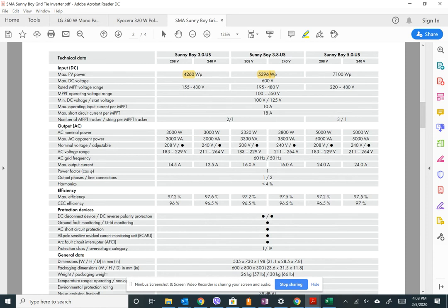Now let's check out some other information. We're going to find the max system voltage. So that is exactly what we did in the last problem. Okay, so I'm going to have you guys do that. So find the max system voltage. You have the lowest temperature, which is -5 degrees Celsius, and you have the other parameters. So you're going to use VOC at STC.